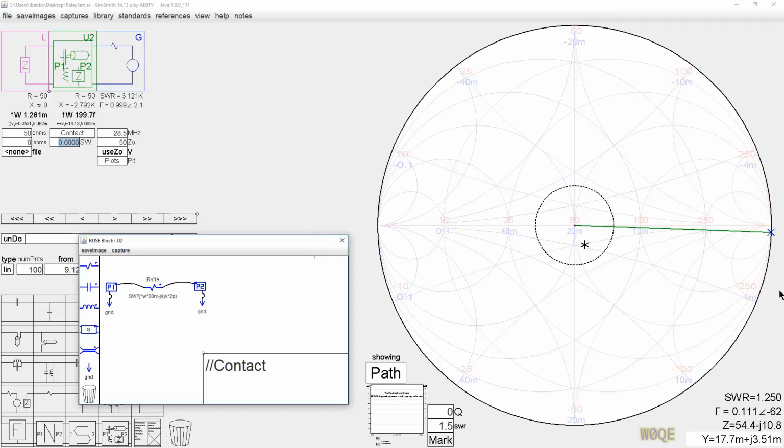So let's look at what we get in a 50 ohm circuit here. If the circuit's open, our impedance is no longer infinity. Our impedance out here, it's a big value in parallel with 1.999 picofarads, it should be this one here. It's 50 ohms in series with 2 picofarads, which is exactly what this circuit is, 50 ohms and 2 picofarads here. Likewise, if I operate the relay, when I operate the relay, it's a non-zero value. The relay's released at 0.